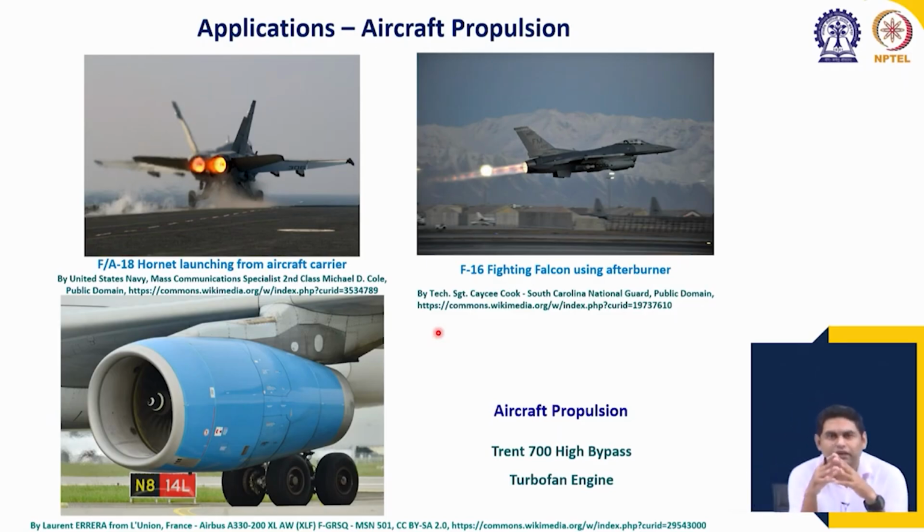development, in the early 1900s, aircraft were designed with engines which were similar to or derivatives of automobile engines. At that time automobiles were also new, and these mechanical systems were new inventions. So, reciprocating automobile engines were used for running a propeller, which generated thrust and propelled the aircraft forward. These had multiple difficulties in the sense that they were very bulky. There was an issue with lubrication and long term maintenance or usability.